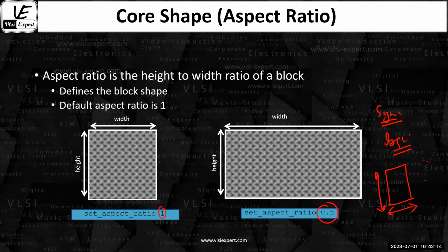So for each and every standard cell, you know the size. If I say NAND gate, you can say yes, the NAND gate is going to take this much area. Inverter is going to take this much area. Adder takes this much area. Flip-flop takes this much area.